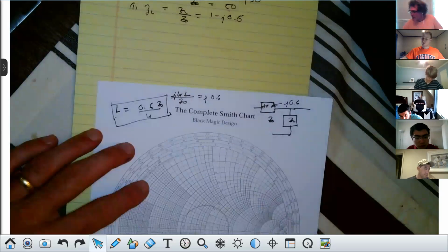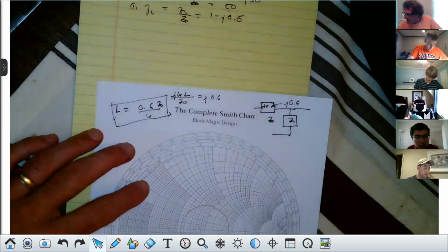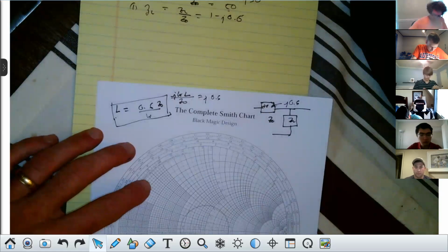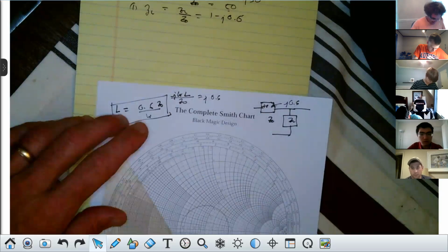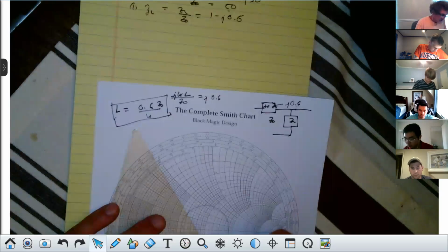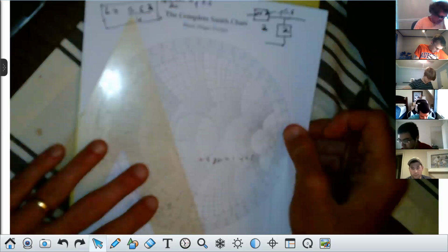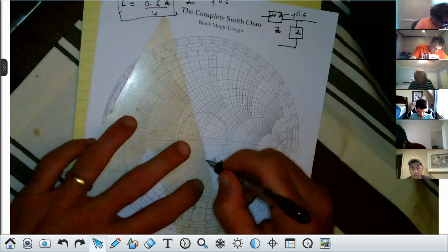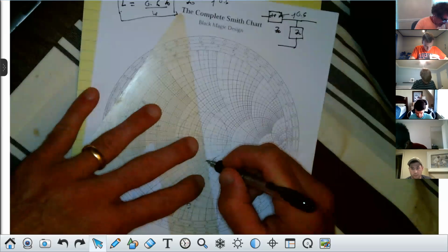And then get your straight edge. I have drafting tools, so I'm fortunate. Then take your straight edge, and I'll move it up so you can see it. The only thing I'm doing now is drawing a line straight through the center of that circle, out the other side.